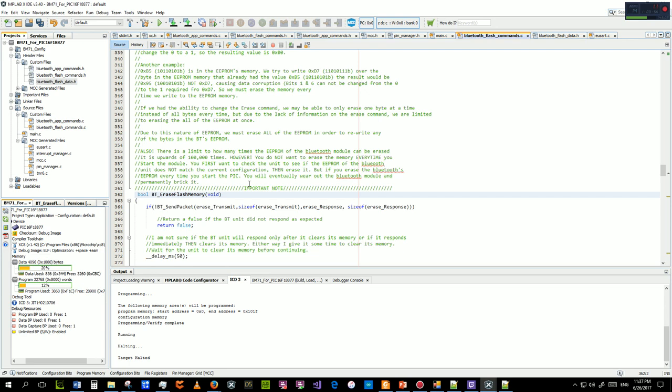Now, if you go to send another piece of data to the EEPROM, maybe the data you send needs to convert a 0 to a 1 because of the difference in the data. The EEPROM won't do it. It'll just stay a 0, even though it needs to be a 1. So now, you go to write a second value to that same byte that you've already written, and it doesn't match either the data you wrote the first time or what you're writing this time, because it creates a whole new value, because some of the bits could flip, some couldn't.